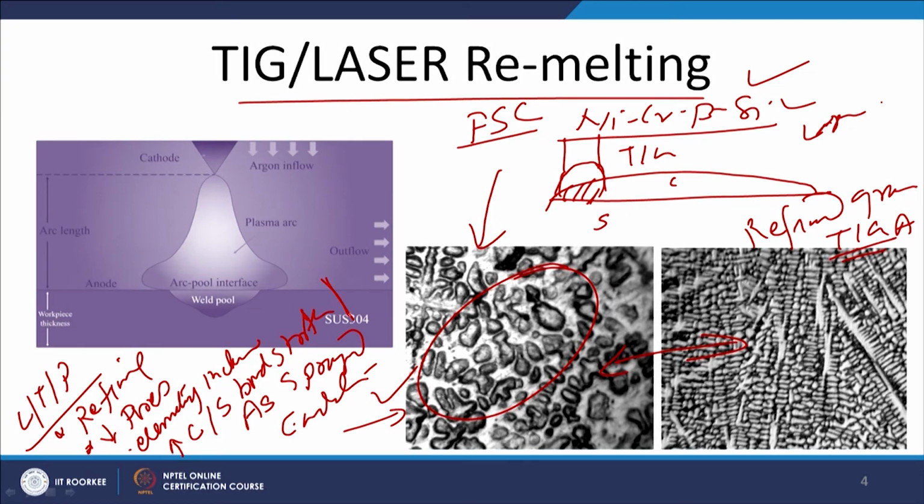The third approach of enhancing the performance of the flame spray coating is controlled alloying. Since the material to be coated is used in the form of powders, which is sprayed through the oxyacetylene flame onto the substrate after heating to the molten state and accelerating it towards the substrate at moderately high velocity.